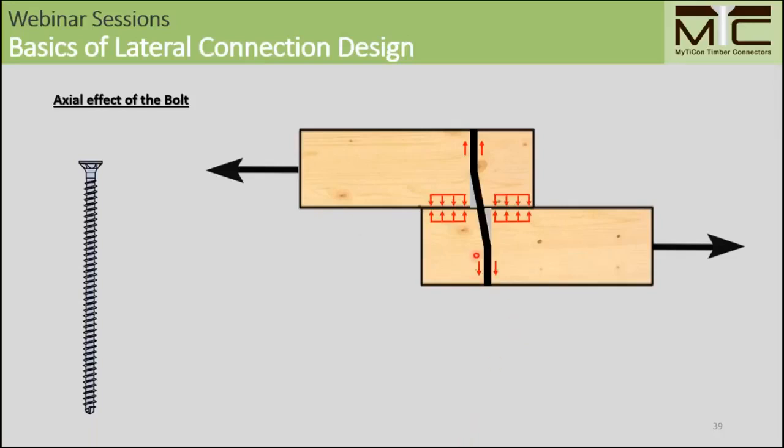In general, we see that the fastener is prevented from being pulled towards the shear plane here. And by being prevented, we have a lesser initial deformation. So the connection is a little bit stiffer in the beginning. And we can also see in ultimate stages that the ultimate capacity will be about 50 up to 150% higher than the capacity with just a smooth dowel. So the Eurocode equations are relatively close to estimating what the scenario in real will look like.